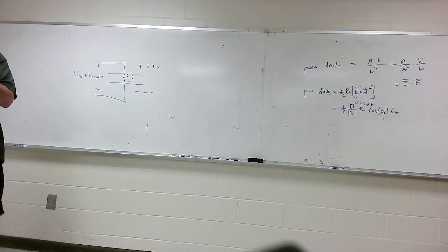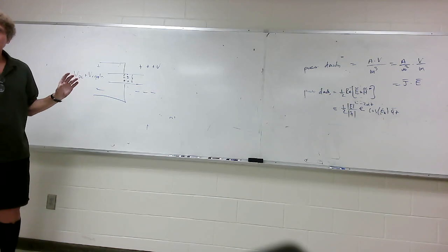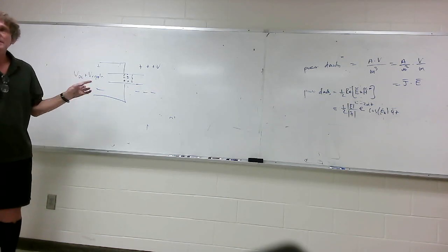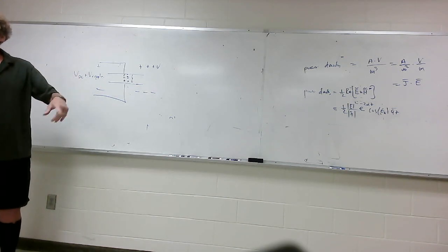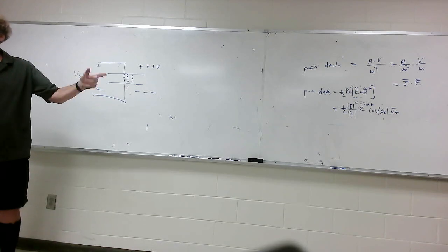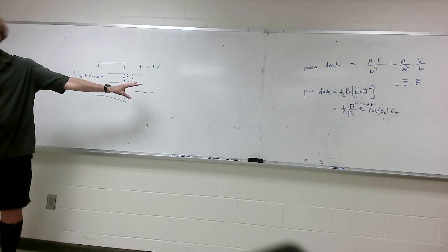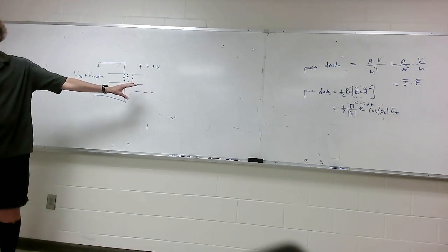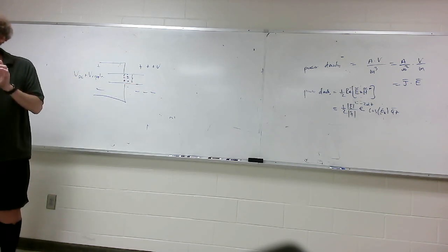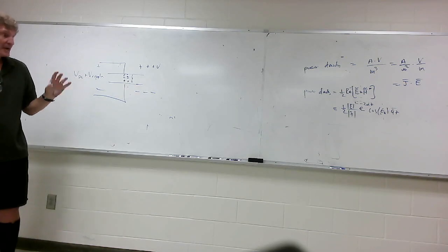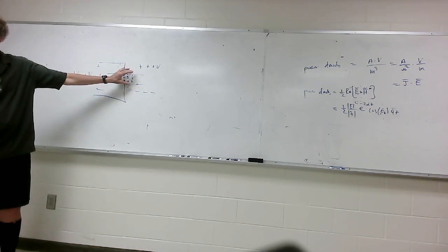And if you have an electrolytic capacitor and you use it with an AC voltage that's flipping, if the voltage is any meaningful amount, any size, that thing will blow up because there's a huge amount of loss. Epsilon double prime is very large for this one. So basically it'll heat up and blow up. You know how a resistor heats up? All right, that's what's going to happen if it's an electrolytic capacitor. Electrolytic capacitors are used for DC, to get rid of DC ripple, basically.